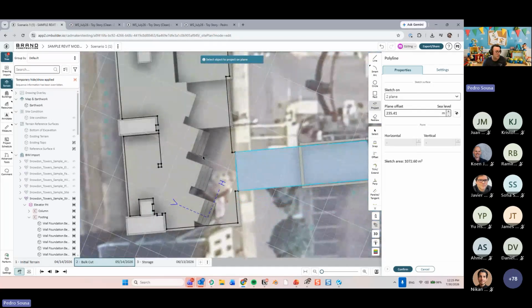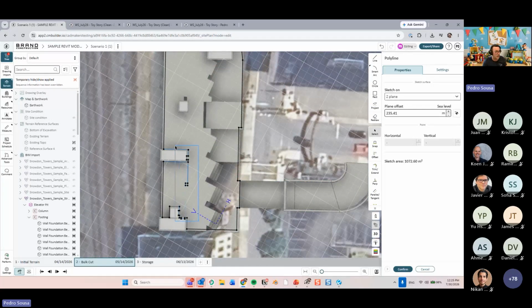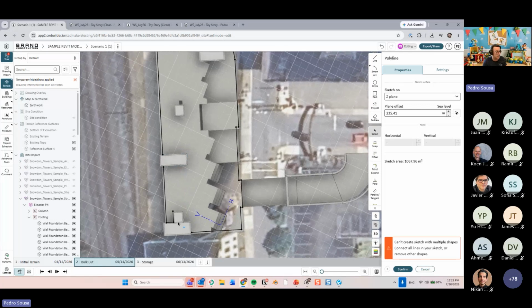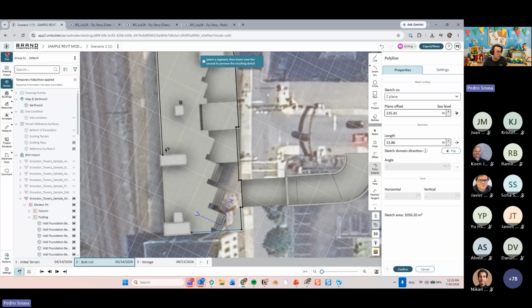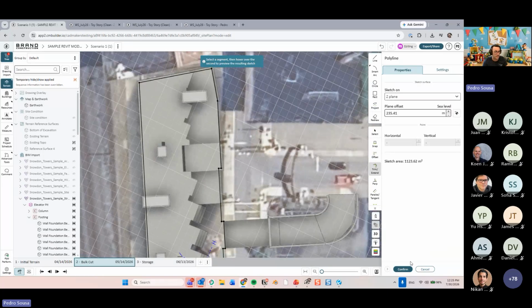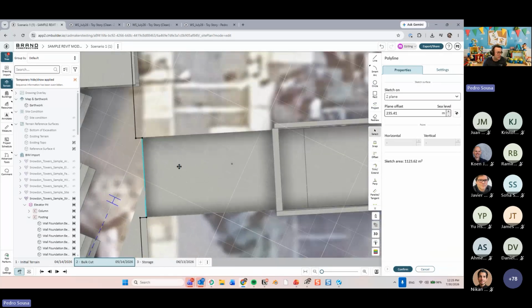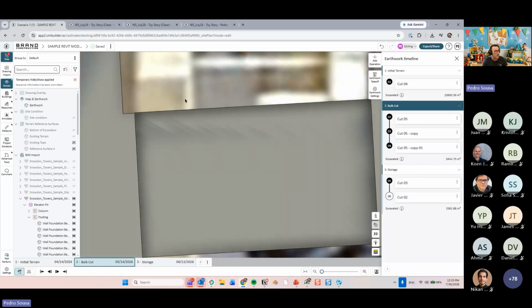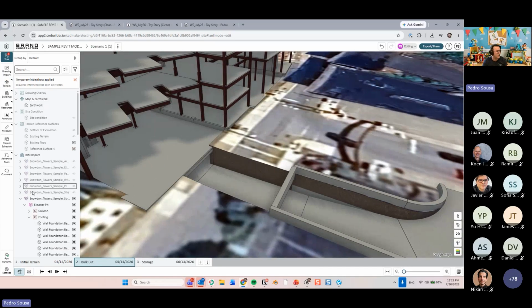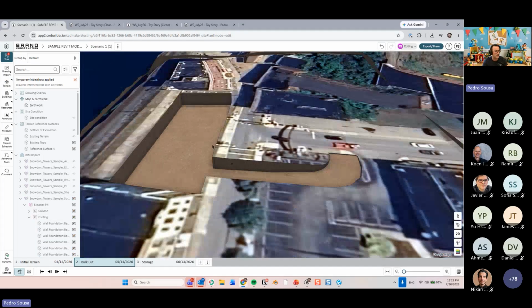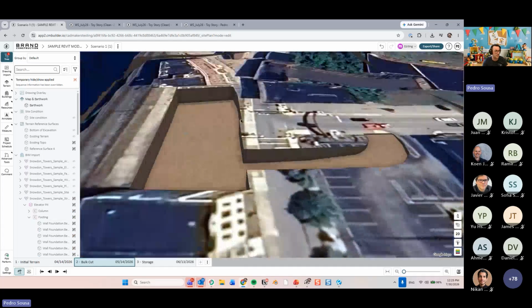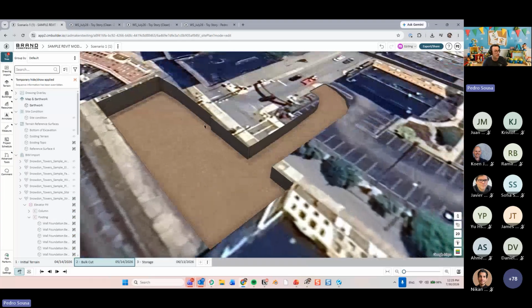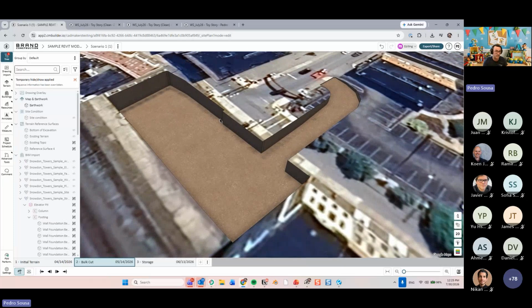Usually the slab on grade shapes are very weird, just like this one, as you can see over here. So I will simplify this by simply deleting all of these lines and trimming this line with this line, and that's it. Okay. And I will extend this part over here so that it interacts with the other cut, just so we won't have a little sliver of dirt over there. Cool. So now, again, if I hide my model, this whole cut that follows the shape of my excavation was created very, very fast and very easily, right?